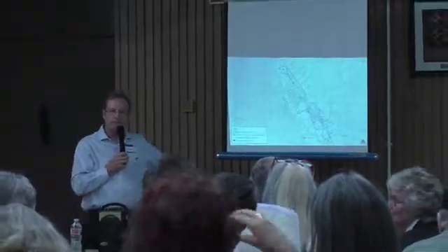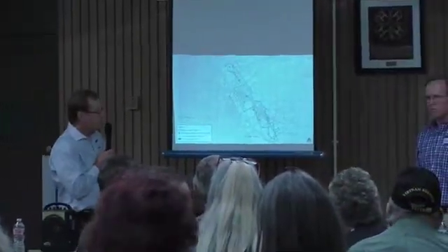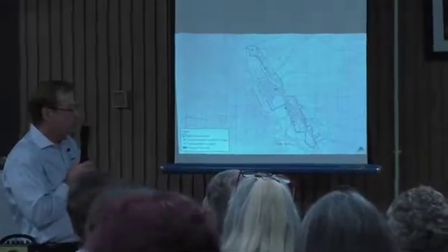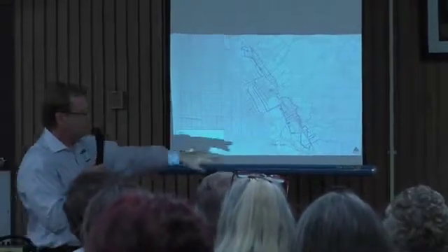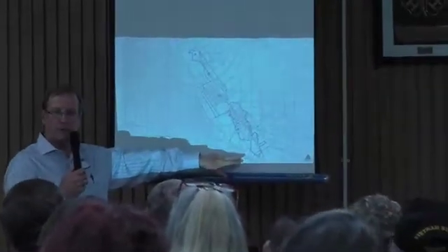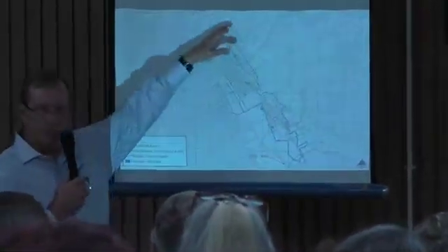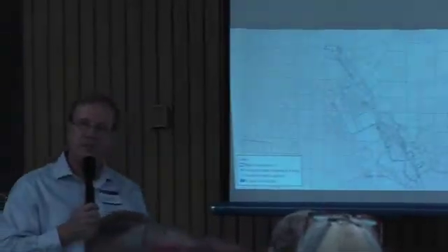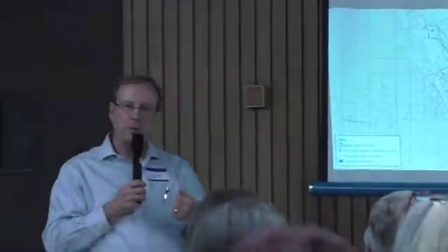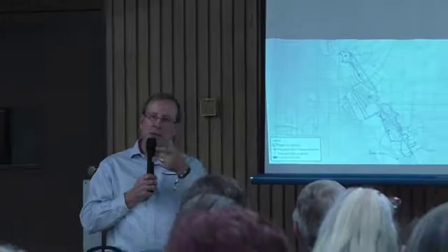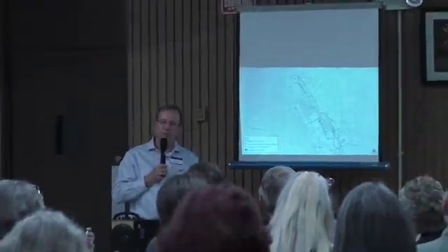Where's your secondary on that? In case there's a fire all around and you can't get into it, the pumps go? What about down by the school, so you have a secondary? No, what happens is these tanks are at high enough elevation, and the lines that are going to be running down the roadways are sufficient size, that the water can be delivered to those locations at a pressure that's suitable for the fire department to use them.